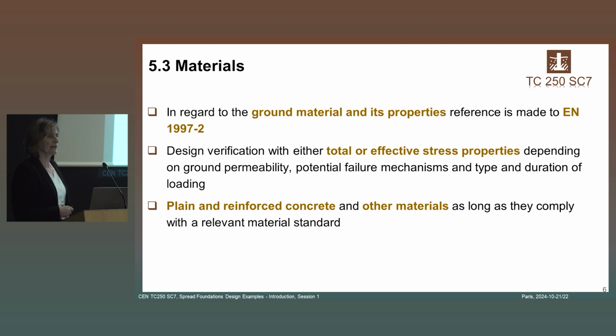Now 5.3 includes some provisions on the materials. So regarding the ground materials and the properties, there's a reference made to Part 2. But it is clearly stated that you may use either total or effective stress analysis depending on the type of problem that you have, considering the ground permeability, potential failure mechanisms, and the type and duration of loading.